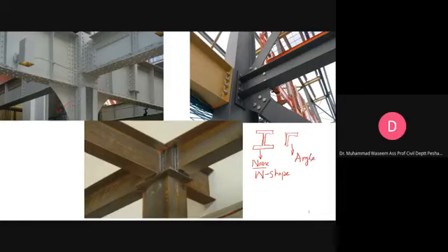So when we design a tension member, a compression member or a flexure member, we have to select these shapes, but these shapes need to be connected. They are connected by bolting, by welding, or by riveting. Please remember that riveting is a permanent fastener. Bolting is different, as you can replace a bolt very easily.